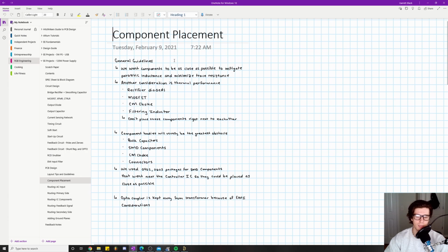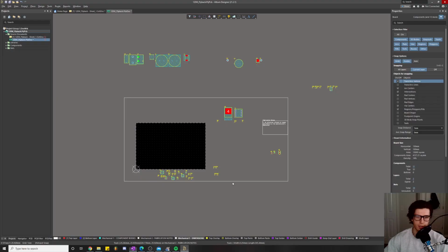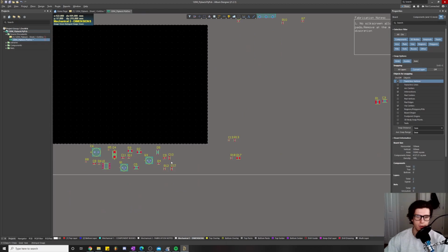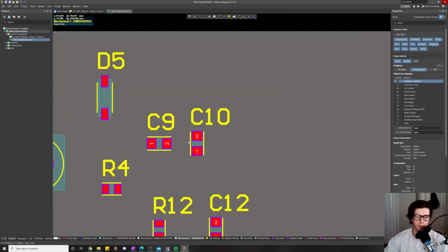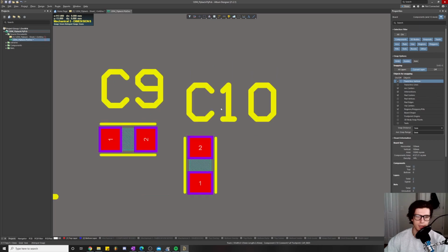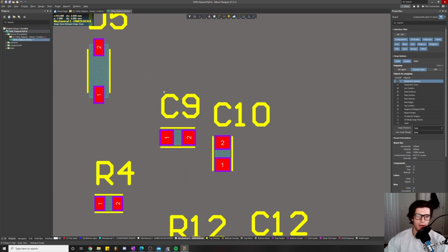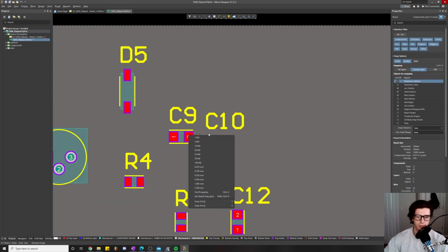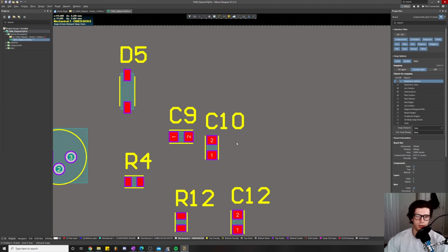But something to consider is that you not only have the component, you have the silk screen to worry about as well. When it comes to placing components, you're never going to be able to place these pads right on top of each other. You're always going to have the silk screen, and you're always going to have mechanical component bodies. Those are going to be your two biggest mitigating factors. So getting one pad as close as possible to another is not really your worry here. So that's what I say about that.